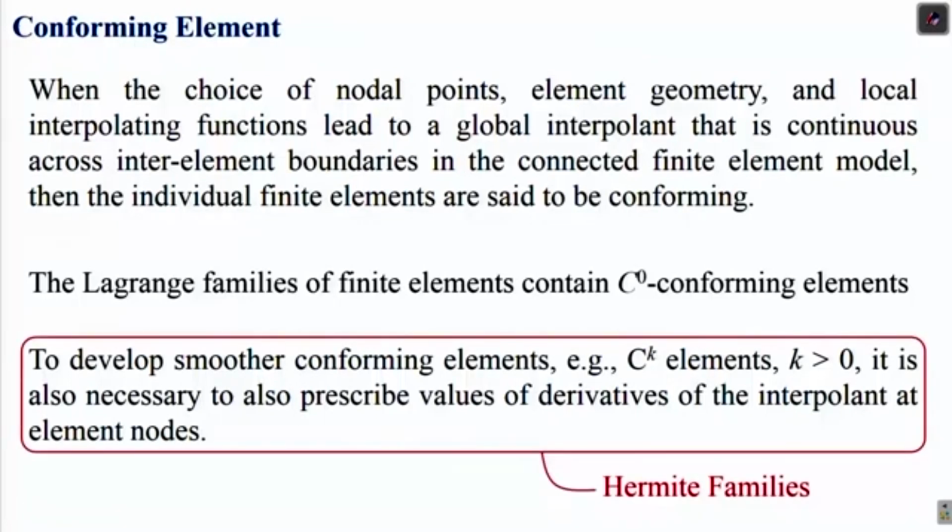That class of finite elements is called the Hermite family, which we have not discussed in the context of two-dimensional problems. In one-dimensional problems, it was extensively discussed how to construct a shape function for a beam problem, which is a member of this family. But for two-dimensional problems as well, we may need the interpolation of derivatives. That all depends on the problem that we are solving, the order of the differential equation, and the weak form.